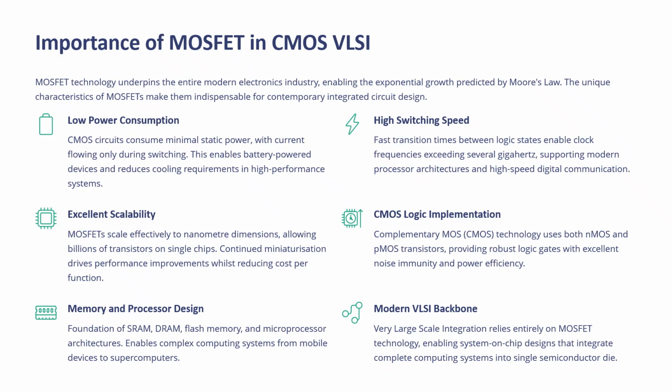CMOS logic implementation: complementary MOS, or CMOS, technology uses both NMOS and PMOS transistors, providing robust logic gates with excellent noise immunity and power efficiency. Memory and processor design: foundation of SRAM, DRAM, flash memory, and microprocessor architectures, enabling complex computing systems from mobile devices to supercomputers. Modern VLSI backbone: very large scale integration relies entirely on MOSFET technology, enabling system on chip designs that integrate complete computing systems into a single semiconductor die.